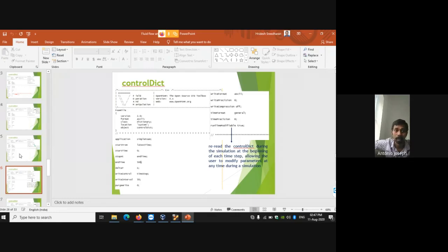Now we are giving adjustableRunTime as true. That means I am giving some time step, and with that time step we cannot solve that problem in a convergent way. That will be occurring only in the case of a transient flow. In transient conditions, since it's changing with respect to time, if I'm giving a time interval as 1 second, there are a lot of parameters that will be changing within that 1 second.